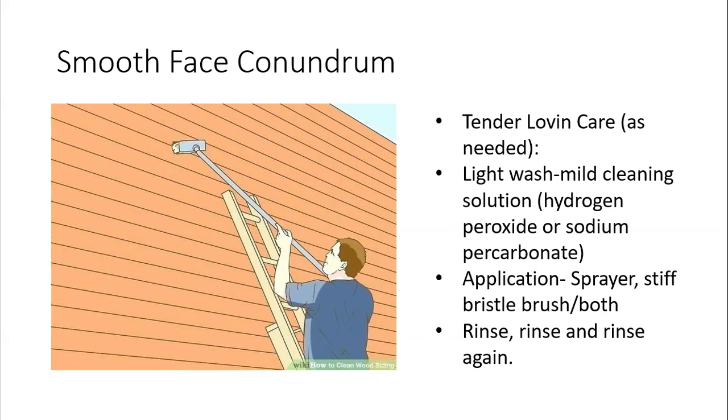So the tender love and care, it's our firm belief that only people who love wood enough to take care of it should use wood, and those people who don't want to take care of wood shouldn't use wood. Or if you're going to do it for no maintenance, and we can get into that, you prep it exactly right and know what to expect. You can do it with no maintenance. Just be ready for it to turn gray and black.